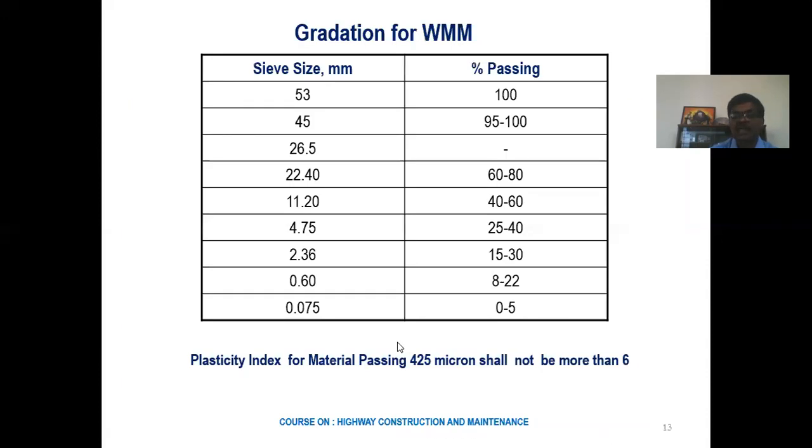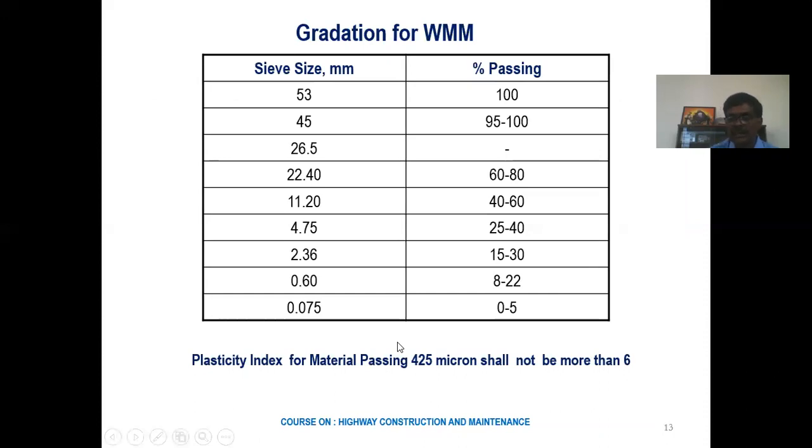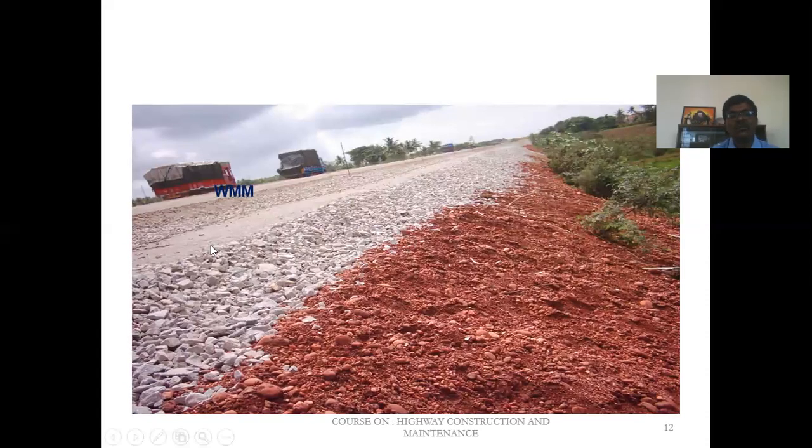Next comes the construction of the base layer. What we discussed is construction of this layer. Practically, the common man does not make out the difference between the base layer and the sub-base layer. Both are crushed aggregates. No soil is there here also. But if you look closely, this will have more voids to have better permeability, and this is a well graded dense mix.